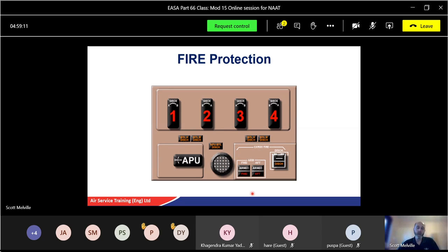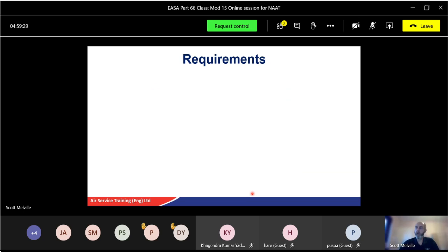But if a manual cancelling facility is provided, it should be reset automatically when the warning has ceased and should not inhibit the main warning system. Okay, so once you've dealt with the fire, reset it. It will come back on if you haven't reset it, if you haven't dealt with it. So you can switch the audible off, but you need some sort of indication as well.